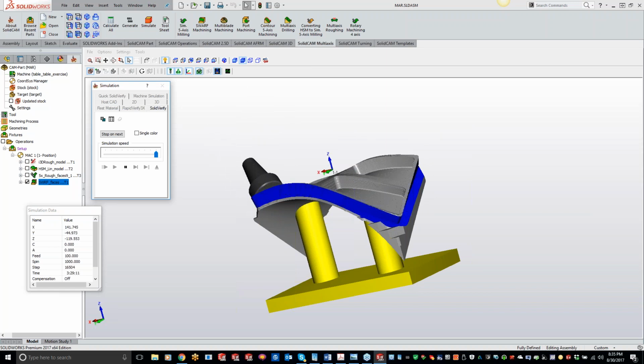I've talked about this in the past, and actually did a quick little YouTube video on this too. When you actually slug out something, you can kind of see where I'm going with this right here, we're going to have a slug in these big bottom pockets right here. What we've said before is we can do the stock splitting right here, and manually turn it off, but as soon as you go to resimulate something, it's going to turn back on for you guys.